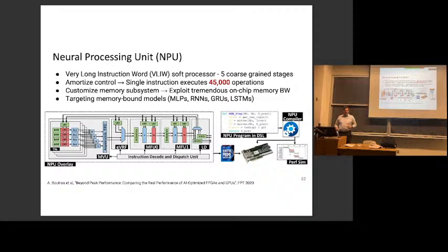Then you'd be accessing 80 registers in parallel. And then these are 2 function units. They're called multifunction units. They just do stuff you need in this kind of neural network: addition, max, scale. So it basically has an instruction for everything. Each operation that you would need in this kind of neural network is inside one of these 2 function units. So they're kind of customized ALUs, and they also are operating with a lot of SIMD again, 40 or 80 elements at a time. And then there's some data movement. So there's a loader that basically figures out where do I put my partial result.